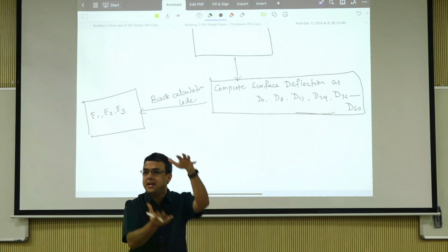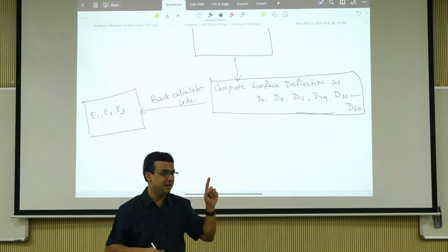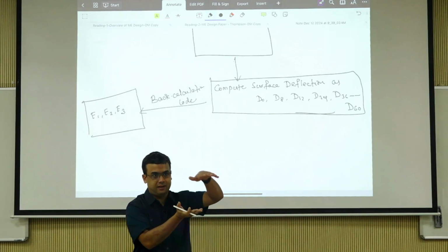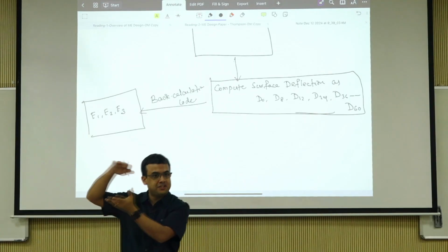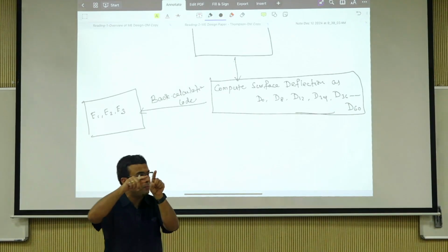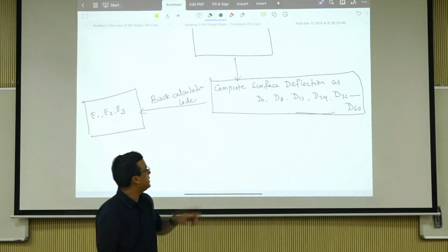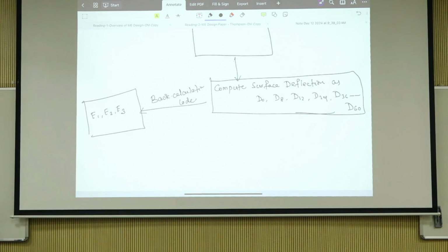Take a complete stress dependent data set and resolve it into one modulus, because the response of a layer with this one modulus is equivalent to the response of the layer which had stress dependent properties, because that is how you matched the surface deflection, right? So this phenomenon is called representative modulus. This E2 now becomes the representative modulus.